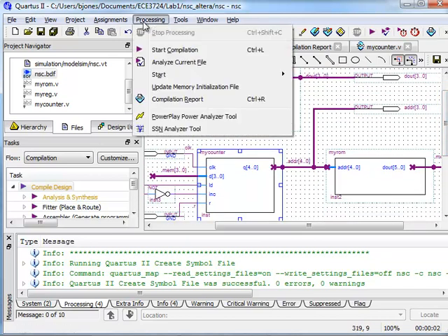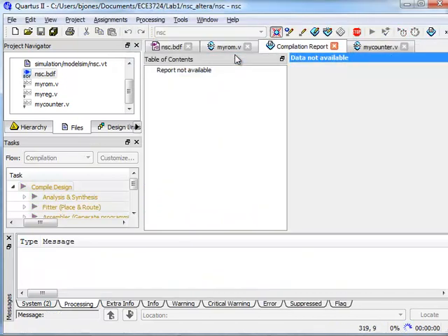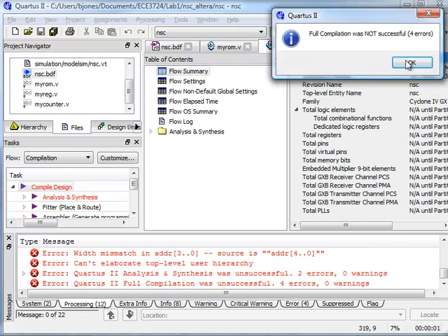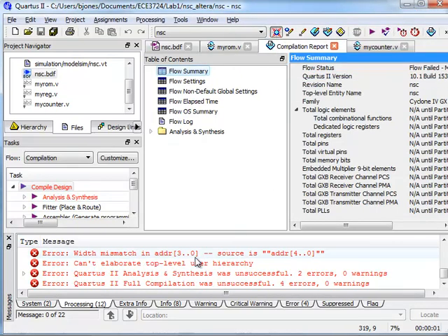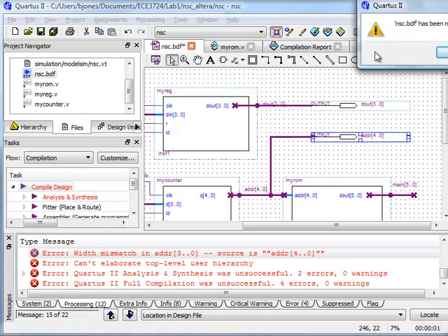Why don't we go ahead and try it again? And you'll notice that iterating on that process will keep helping us. Same sort of error. And notice what's blue. It's blued this, and it's also got a box around this. Aha! This needs to be a 4 down to 0 also. So the tool will help you track things down and attempt to fix all of those errors.